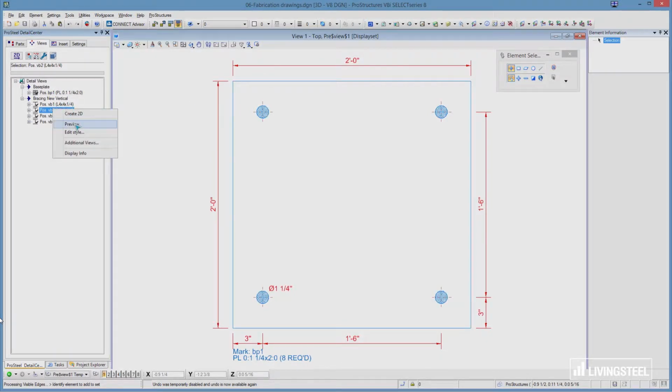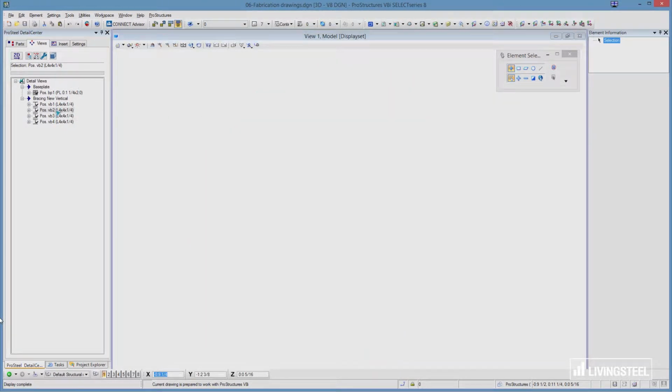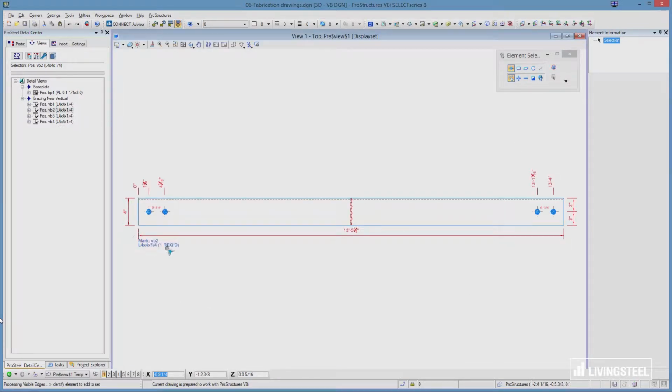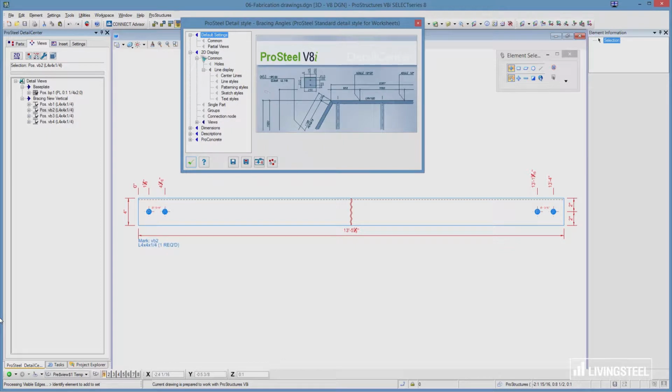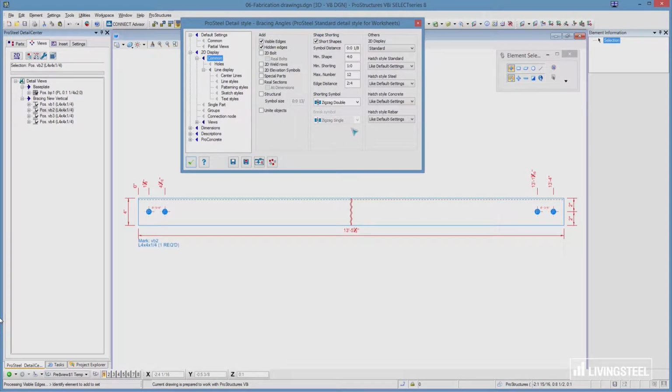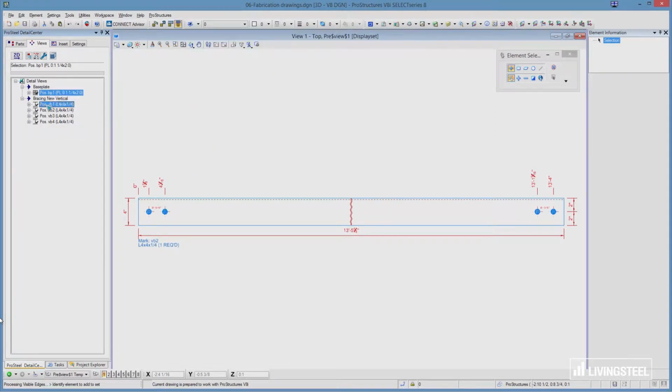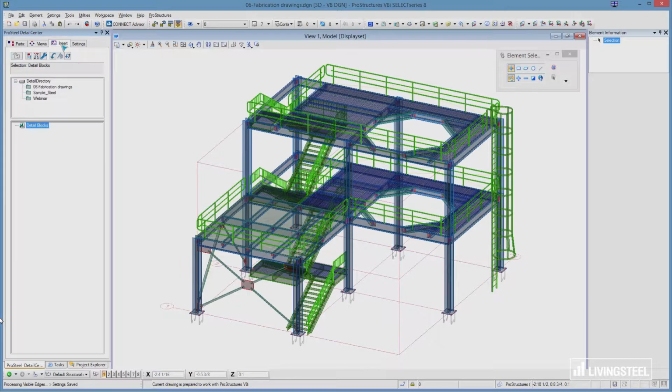Let's take a quick look at one of the bracings. This first bracing that I selected, VB2, there's only one of them, but it's also shortened. So the only difference here between the base plate and the bracing is that I needed to add the shortening information in order to shorten the shape, so that all of my bracings, although they have different lengths, will look exactly the same once detailed. Once I'm satisfied with this, I can transfer all of these elements to the next tab, the Insert tab. In my Insert tab, we can see that we've got now my base plate and my bracings.